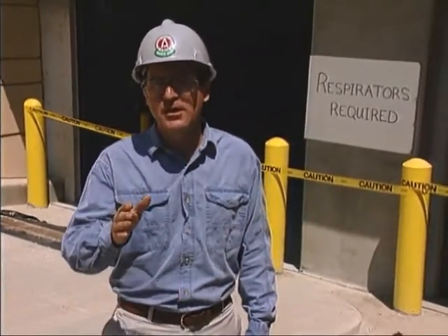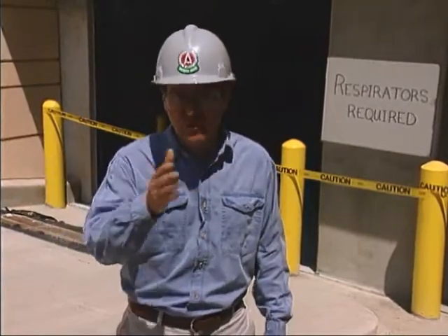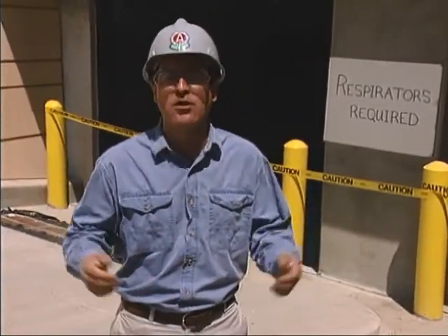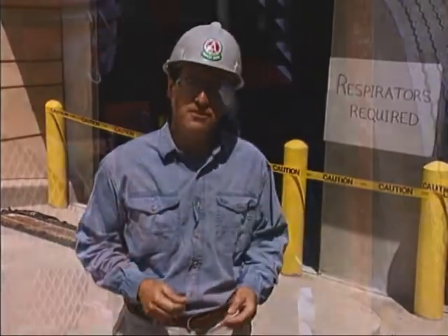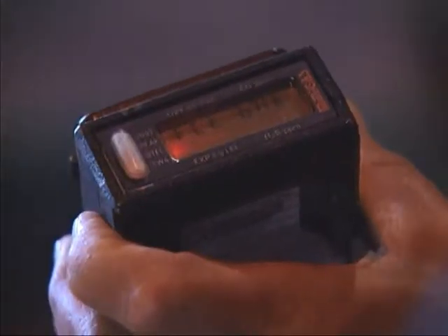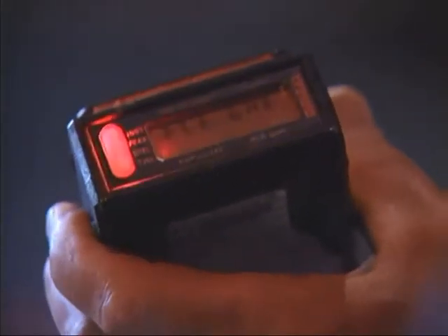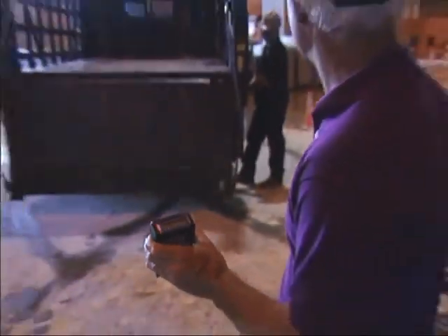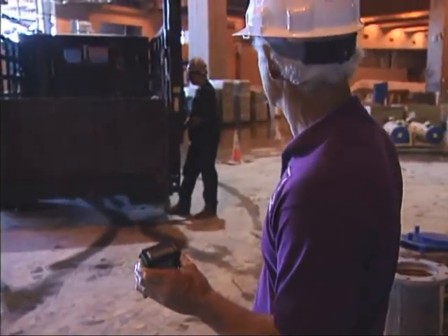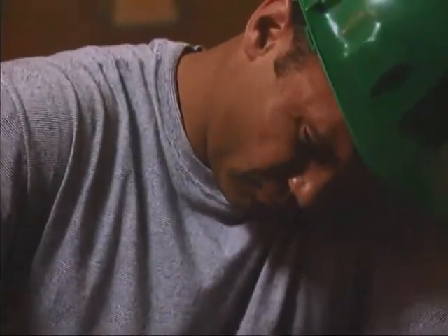So, your TLV and PEL tell you the maximum concentration of a chemical in the air that you can be exposed to over the course of a workday. How is this measured? Many contractors have equipment available to measure chemical concentrations. Others use insurance company loss control departments, trade groups, or private consultants to measure actual worker exposure. These results, compared to the TLV or PEL, can tell you if conditions are safe or not. Knowing these limits is important, but not enough.